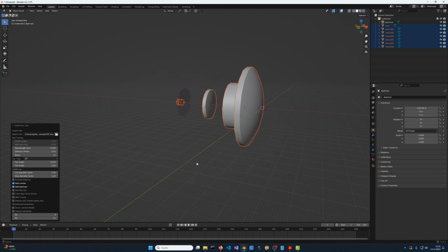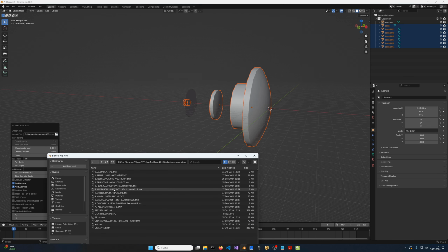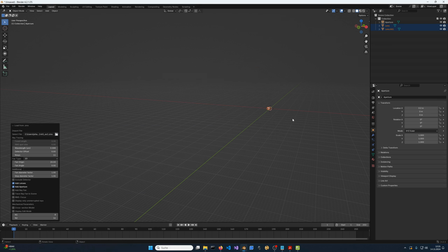So before I actually load the file, again, take note of the overall size of the fisheye lens and its small focal length of 2 millimeters. In comparison, the first mobile design is a lot smaller overall, as you would expect. I mean, you all know how small the lenses in your smartphones are. However, the focal length at 3.33 millimeters is actually bigger than for the fisheye lens. So again, you can see that size and focal length can be very, very different in comparison for different lens designs.